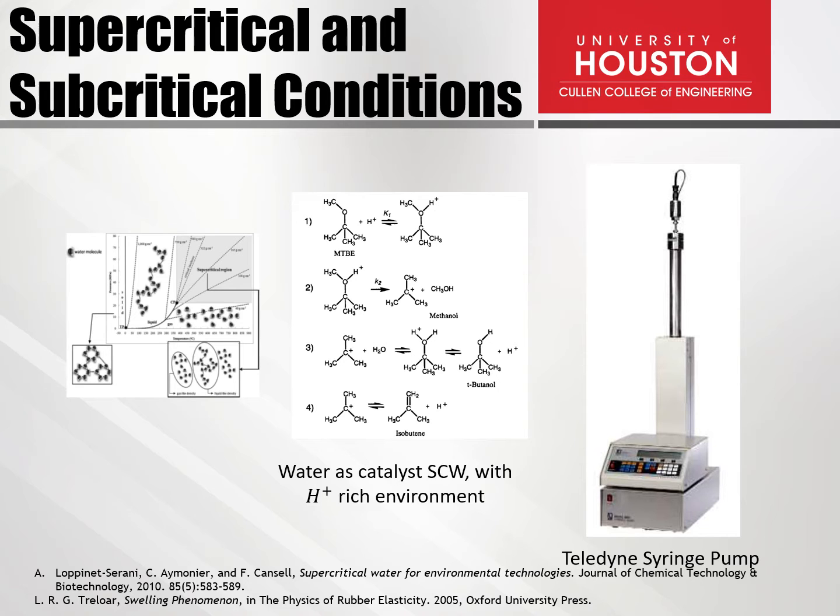For instance, nitrile rubber is mostly stable in water-based solutions. However, in subcritical or supercritical water, it may not be the case. Free radical type reactions can happen, which no doubt should be taken into account in chemical-induced degradation. This is of critical importance as we design elastomer components that work in harsh environments.